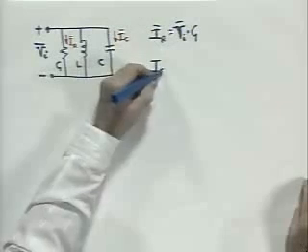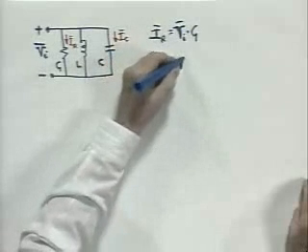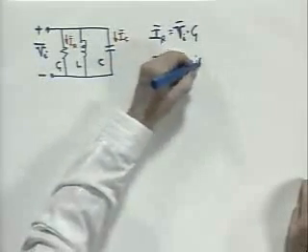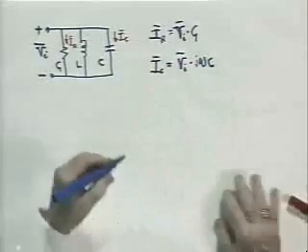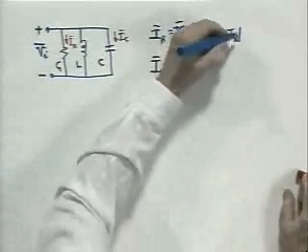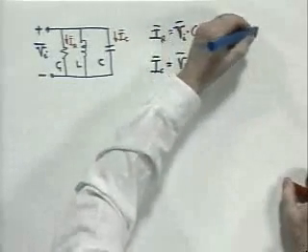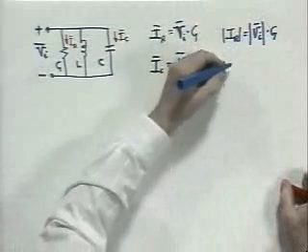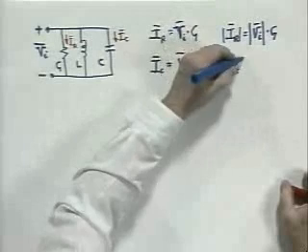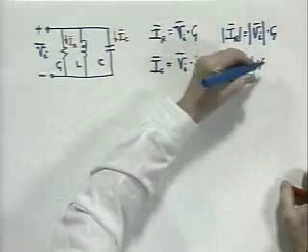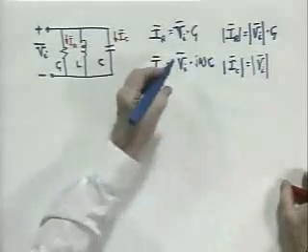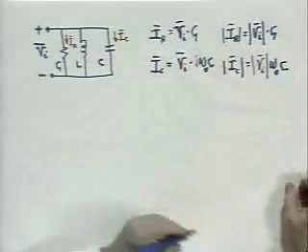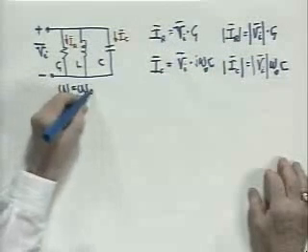The current in the capacitor is equal to the complex amplitude of the voltage multiplied by the admittance of the capacitor, which is j omega C. So the magnitude of the resistive current is just the magnitude of V sub I times G, and the magnitude of the current in the capacitor is just the magnitude of V sub I times the magnitude of j omega C, which is omega, in this case omega naught, times C, because we're driving this at resonance, at omega equals omega naught.